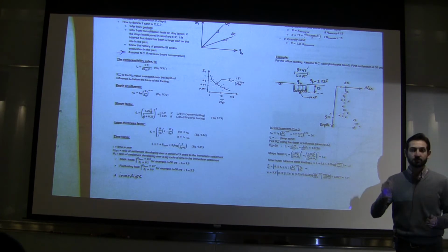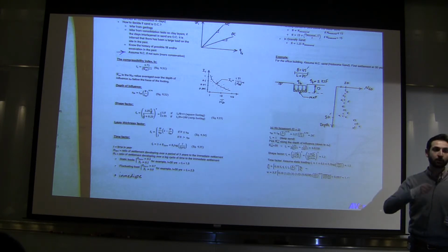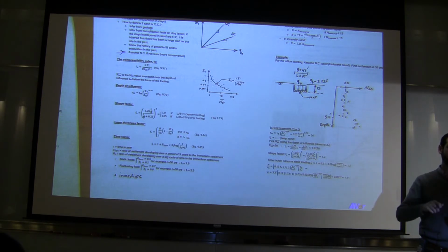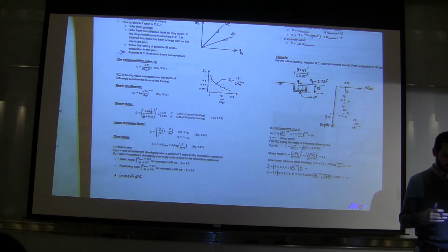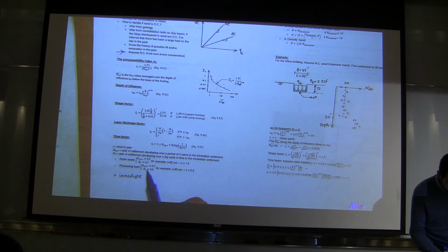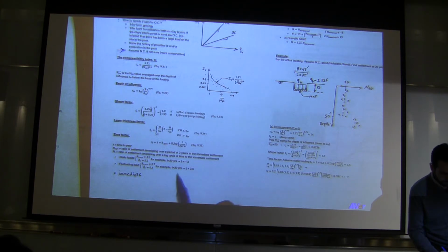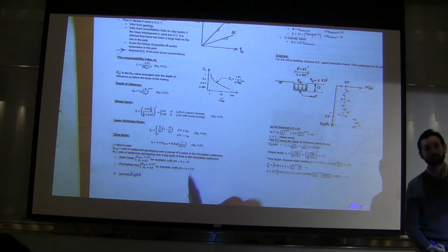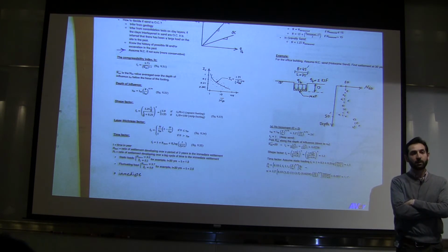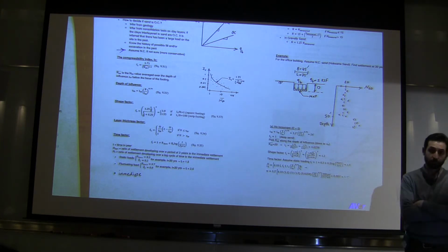Fluctuating loading is something that keeps loading and unloading with a frequency of, say, one second. So the load keeps going up and down in 1 second. A warehouse is not a static load, but it's not as dynamic as mechanical foundations. So these parameters will be a little higher, and after 30 years, that factor is 2.5. So again, the same example that I just said. If your immediate settlement is 2 inches, how much extra settlement do you get from a fluctuating foundation after 30 years?